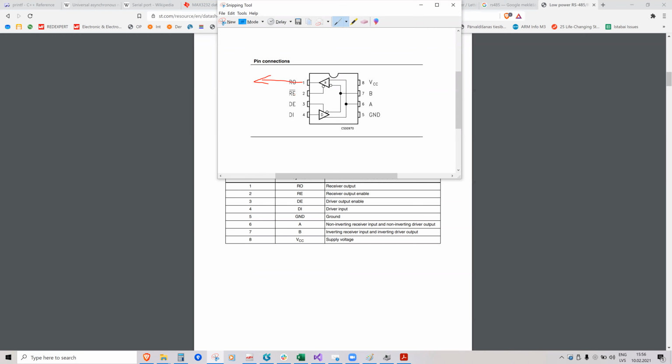Then you have a switch with which you enable or disable this buffer. Usually people just have it turned on all the time. Or they switch it off when they are sending out. So actually you control it. Then the second signal is enable transmission. So you only set it high when you want to send the data out. For the rest of the time, it's switched off. And then data in. This is the TX of the microcontroller with which it sends the data to the lines.